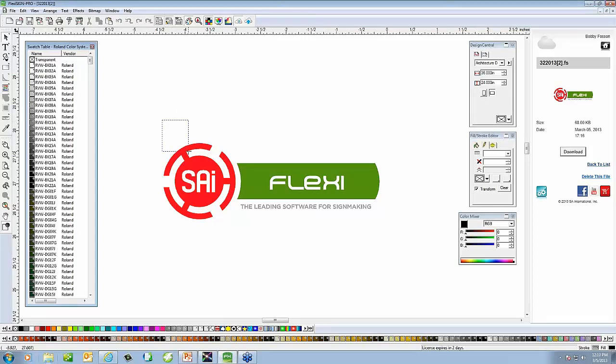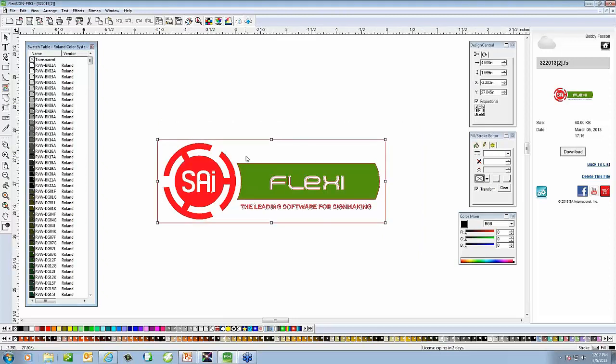So from here, we'll go ahead and we're going to select this object, again, print cut with spot colors, and we're going to actually choose the Send to VersaWorks option. Now, your VersaWorks does not have to be open in order for you to send a job to the queue. Once you actually open the VersaWorks software, it's going to have that holding in the queue and be ready for you to output, make changes, and so forth from there.